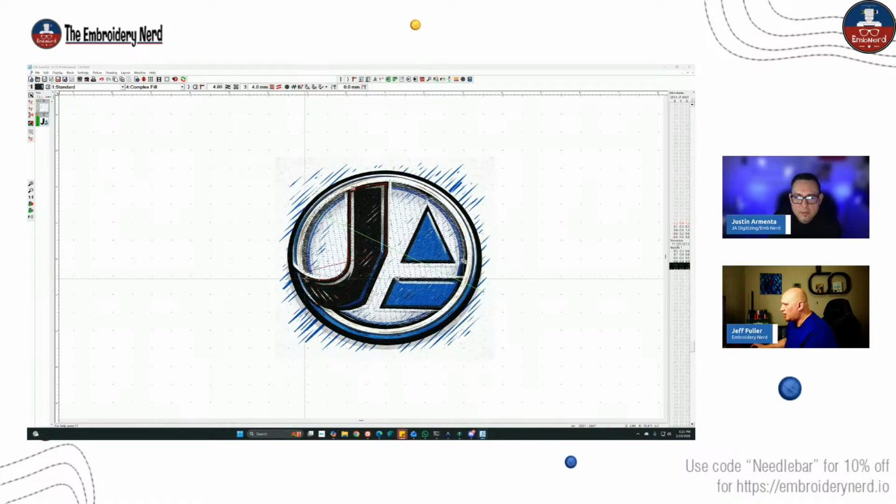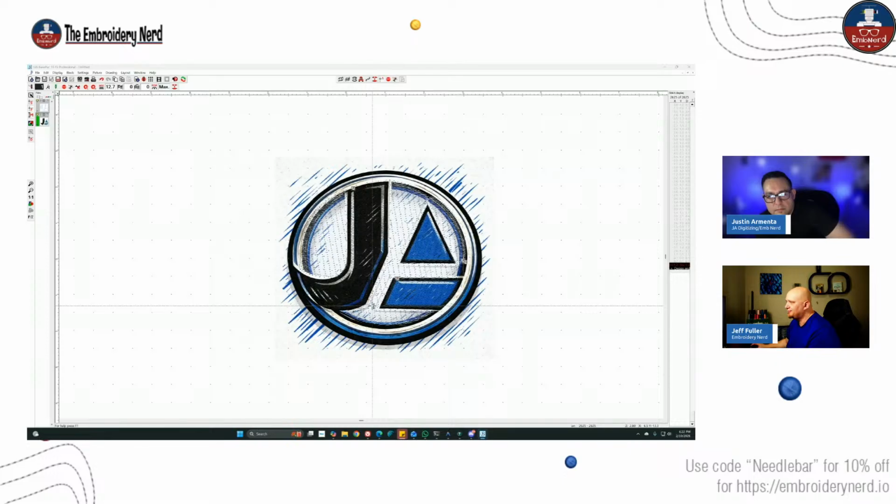I wanted to end this J at this edge of this item and not where I did. So I'm going to back that up one more. You can see I can go back and re-edit based off of the objects themselves, which is kind of nice. You can just roll back, delete points and change things. From there, I believe I ended right there. Sometimes, to double check, I'll do that. So that works for me.